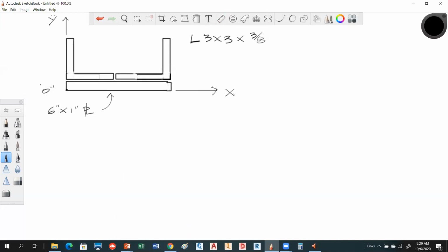There's something on here that's really important. We have what's called symmetry going on. So if this is 3 and that's 3 and this is 6, you should be able to tell me right now that the axis running through here would be the balance point. This balance point is going to be a little bit harder, but it's going to flip up a little bit in here. So we're going to have the YY centroidal axis somewhere here, but I guarantee you this one should have a value of 3 coming this way, okay? Everybody okay with that?